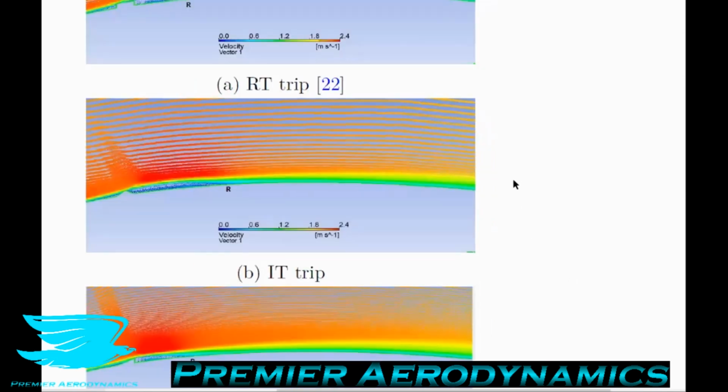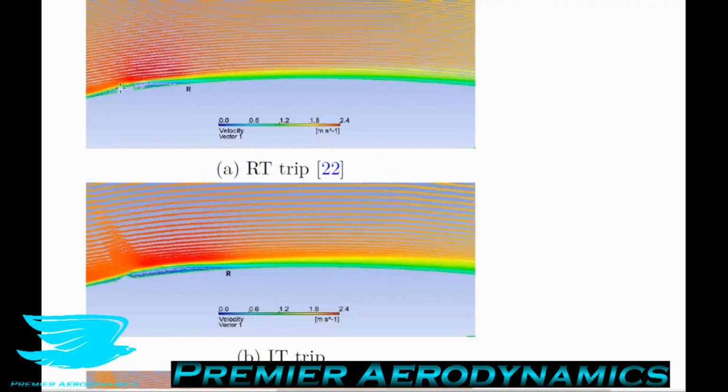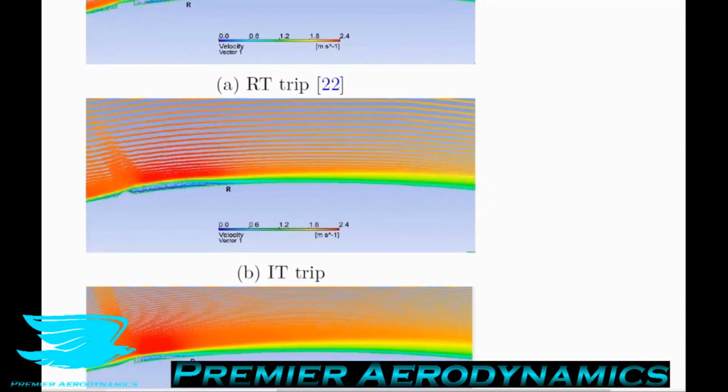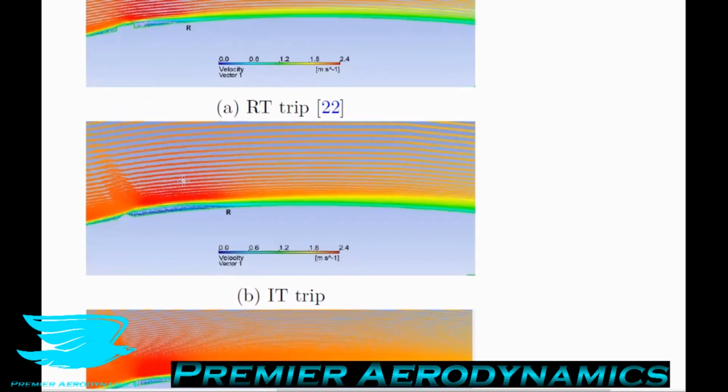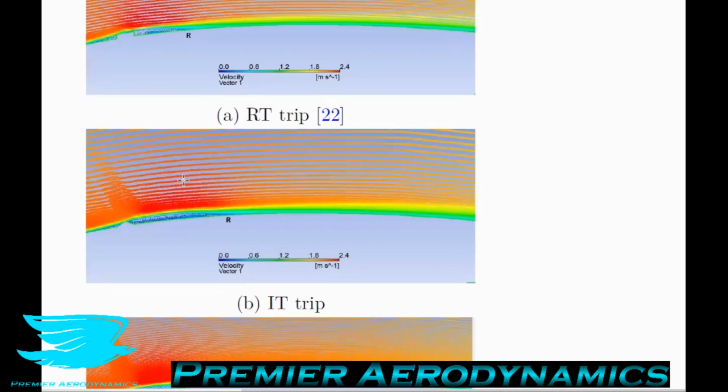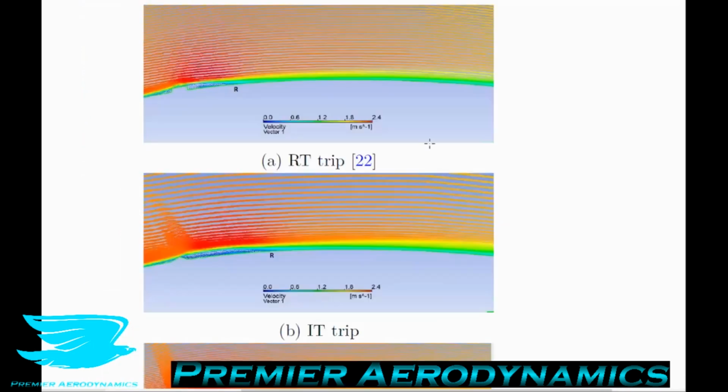Let me zoom in a little bit so you can see this a bit better. So we can see the boundary layer trips just here, and let me scroll down a bit, here. And behind there, we get a little bit of recirculation zone, but the LSBs are largely, I'll zoom out a little bit more here, are largely eliminated. So a recirculation zone is observed just downstream of the BLT, where the transition of the boundary layer from laminar to turbulent occurs as reported in other studies.